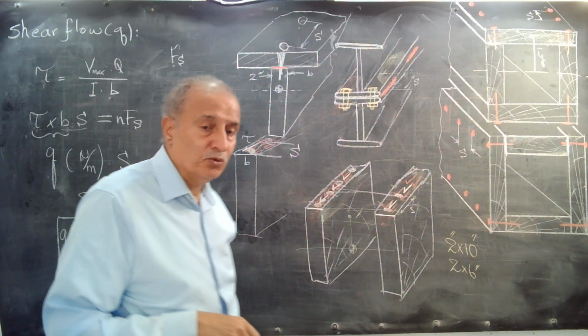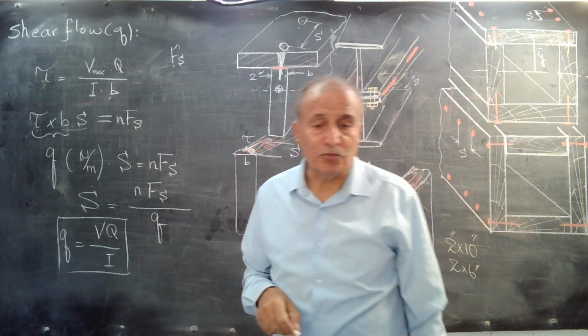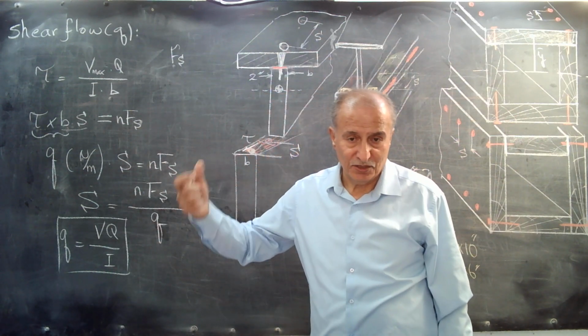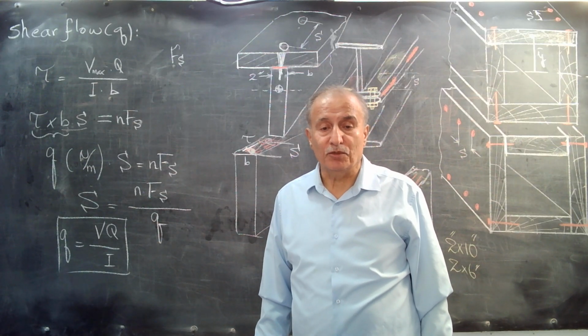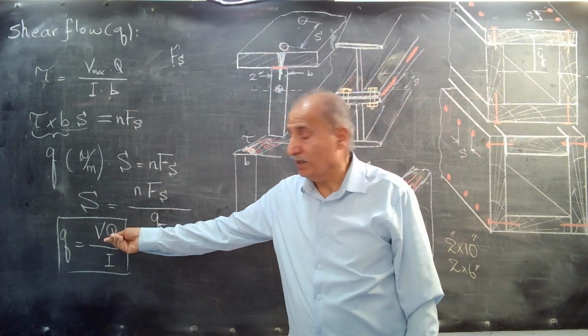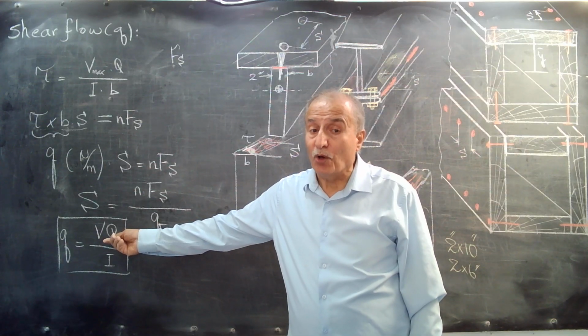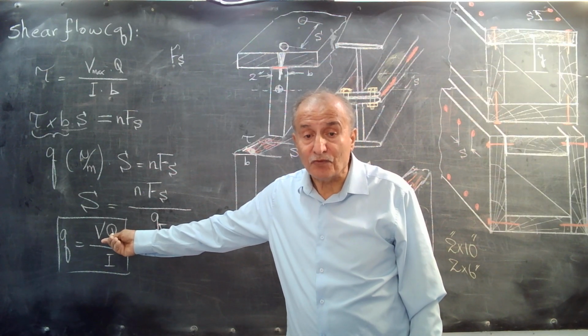But we always look at the maximum shear force in the beam, and this V max needs you to draw the shear force diagram to find out where it is maximum.